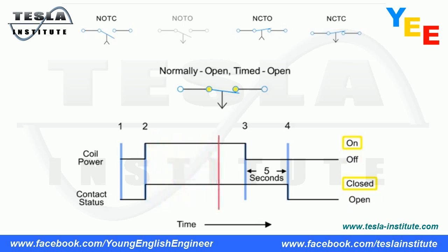However, unlike the NOTC contact, the timing action occurs after the coil is de-energized for 5 seconds. Thus, the contacts close immediately when the coil is energized and open 5 seconds after the coil is de-energized.